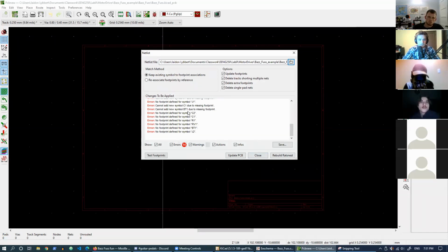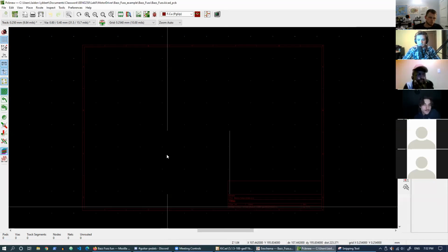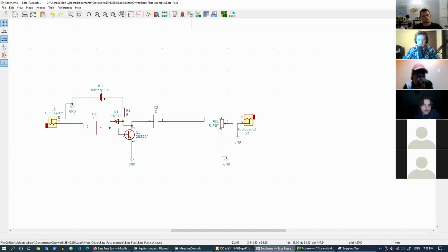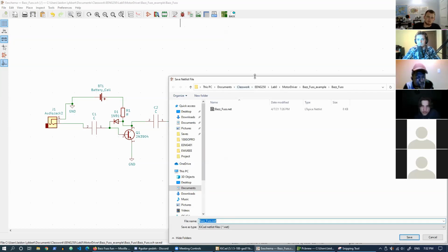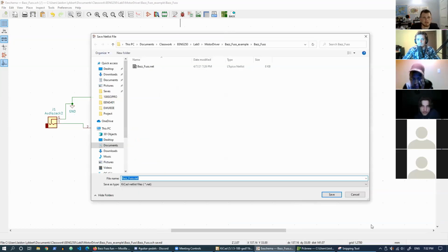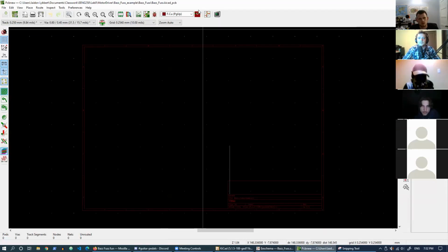Cannot find, oh, missing footprint. Okay, I'm going to have to re-export the netlist. Apparently the footprints are in that. So something I do is you could just save this, and then back in the schematic editor, there's an update netlist from schematic button or something. Gotcha. So as long as this is saved, then it's somewhere in here probably. That one. Yeah, I'll try it and see.